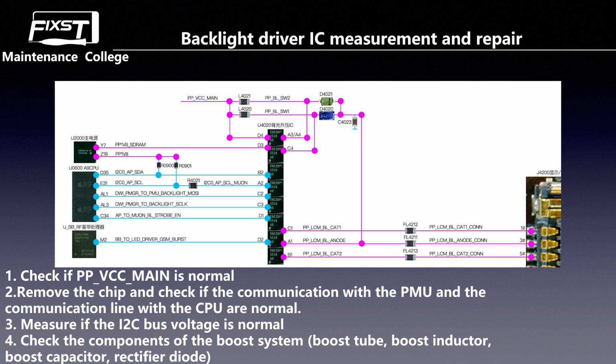So if the backlight circuit is not on, we need to test the U4020, the backlight driver IC. We can change the U4020, this backlight driver IC, to have a try. Change a new one to have a try.